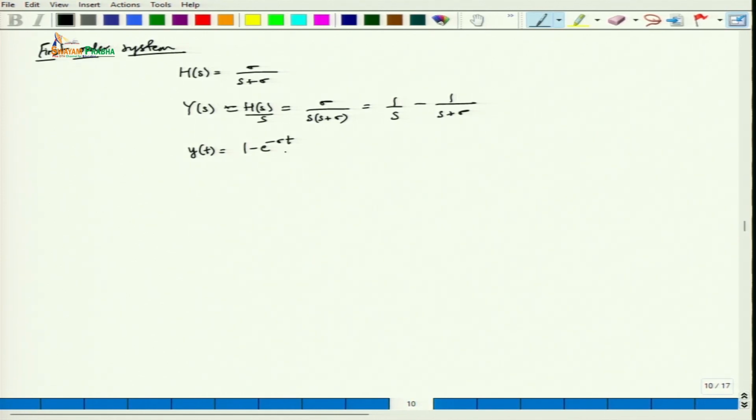So in this case one criteria could be the settling time. It has to settle, and if we perform the same method which we did for the second order system, settling time is 4.6 divided by sigma.